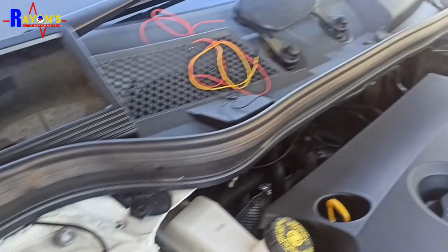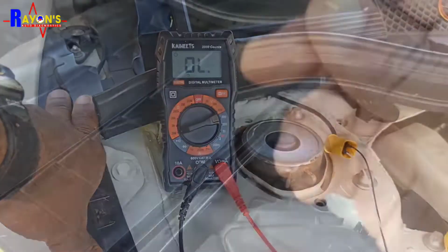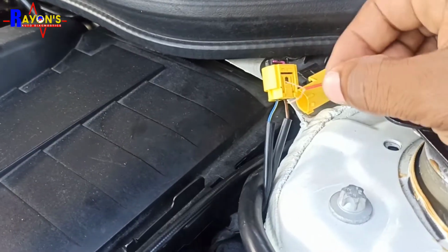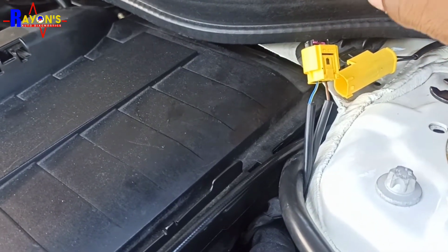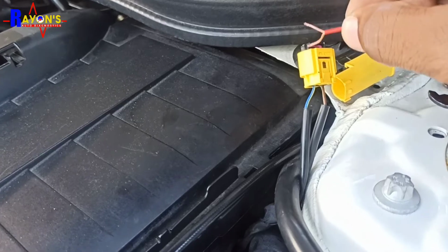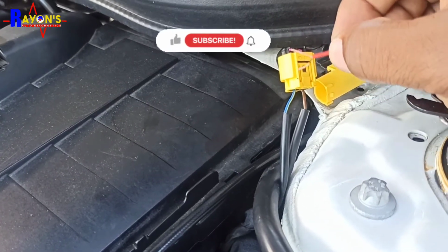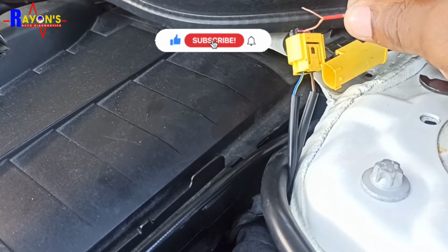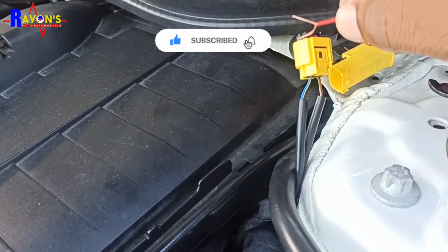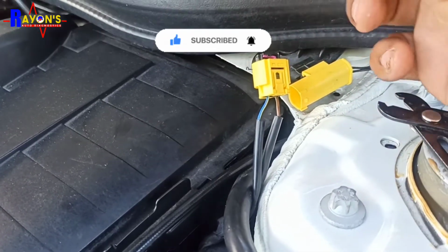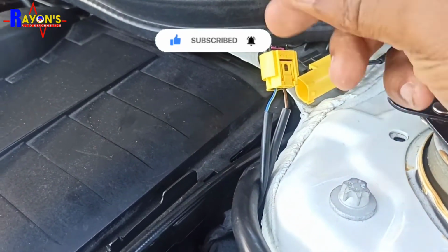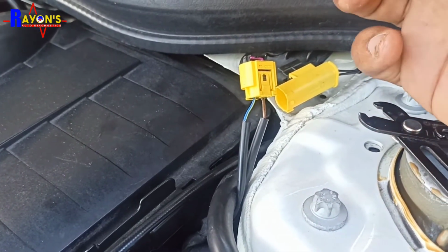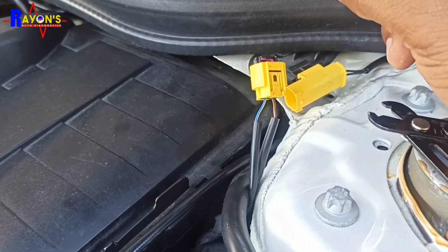Now let's move on to the circuit integrity test. So all I'm going to do is jump these two wires. This should produce a short circuit code. If this produces a short circuit code, it simply means that the computer is registering the fault and the circuit integrity is fine. From the moment the computer is seeing it, the computer is able to respond to the system. So we wouldn't have a wire problem, and we wouldn't have an airbag module fault.